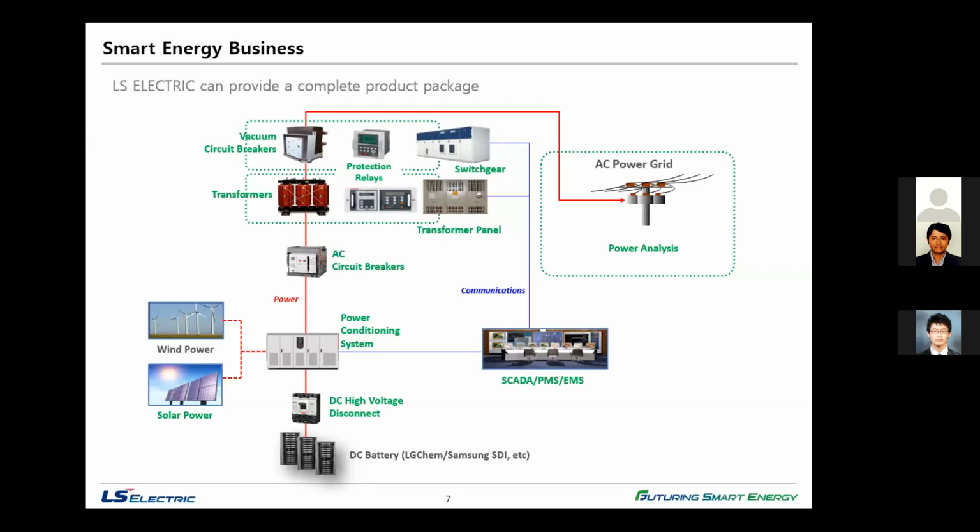So now looking at the power conditioning system, this is basically two-way. When we talked about PV inverters, they were transforming from DC to AC. This PCS does both ways, from DC to AC and AC to DC as well. Why we need to transform power from AC to DC is that we actually need to charge from the grid.